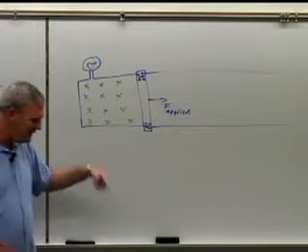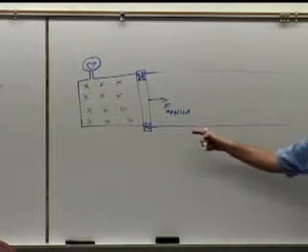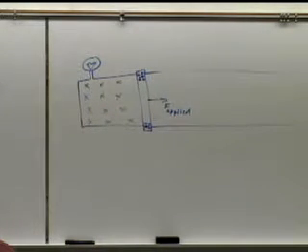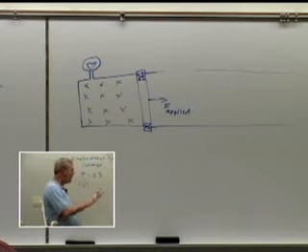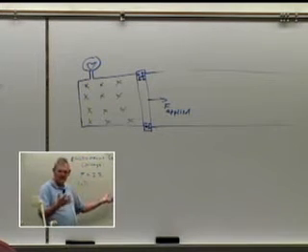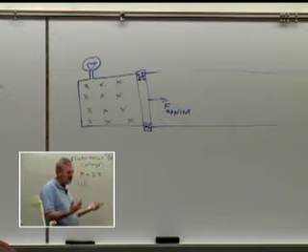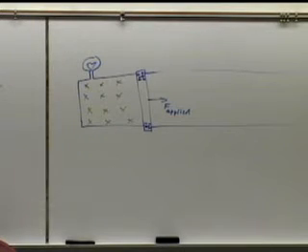Because eventually the magnetic force that we create is going to equal that applied force because we're going at a nice constant velocity. If I speed it up, if I push it harder, it'll create more current. It'll create more energy in there. If I slow it down, it'll create less. If I stop it, it won't create any. So, how do we get our EMF? That's what they were talking about in the book when they talked about electromotive force.